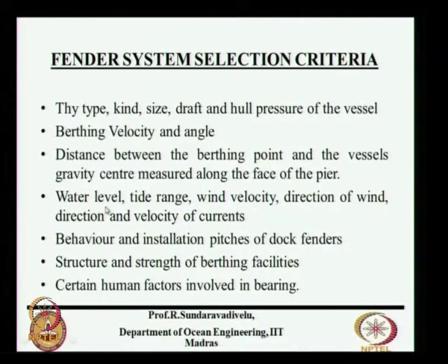This water level we have already explained, tide range also we have explained. This wind velocity is when the vessel is in position, this will be important, direction of wind and velocity of currents. Behavior and installation pitches of dock fenders, that is the interval at which we have to put the fender.